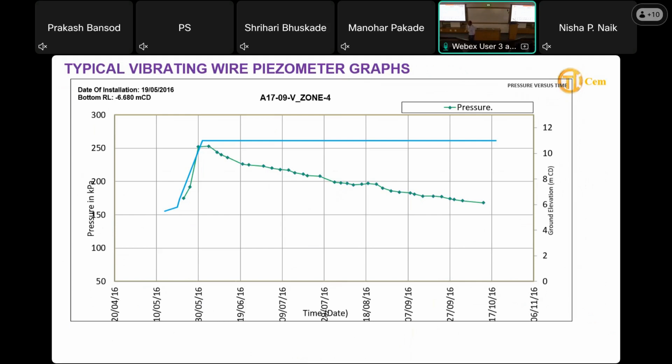Seasonally there is a change, but here every day two times it comes, two times it goes. So whenever you are taking the reading, you need to understand the time. That's what we did: we put in an observation well, took the reading, saw how much the level is there, and then adjusted this level while interpreting. Otherwise, it may mislead your data.